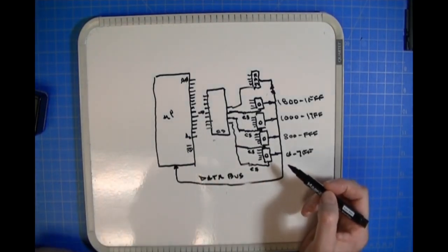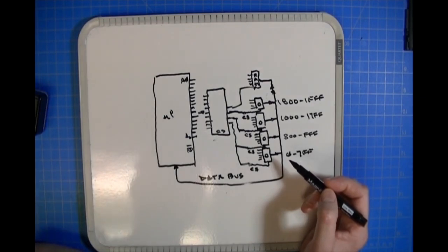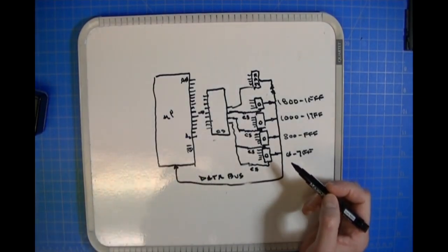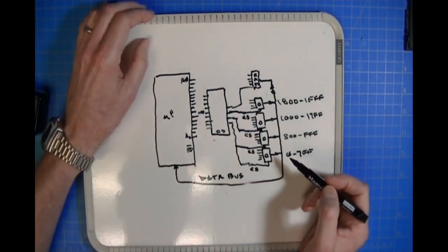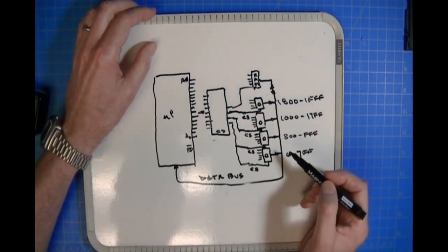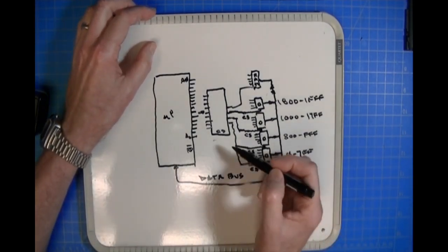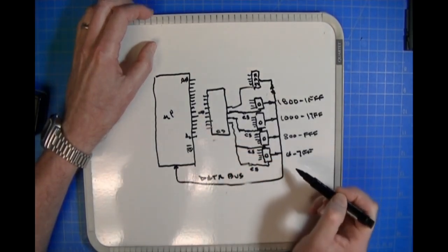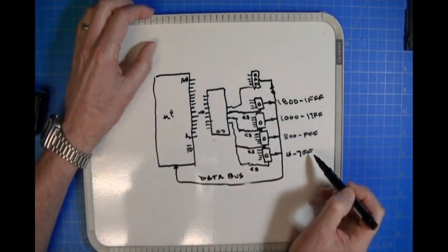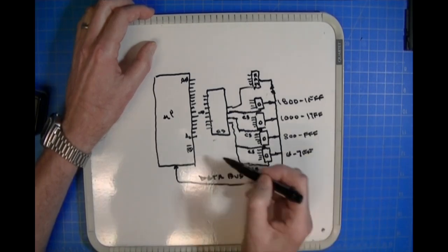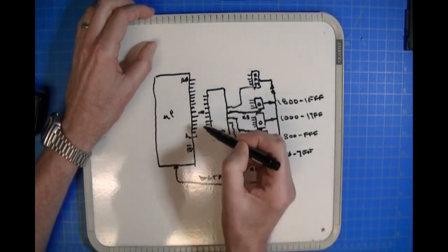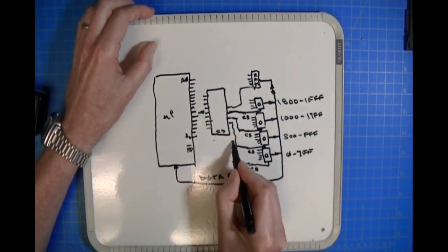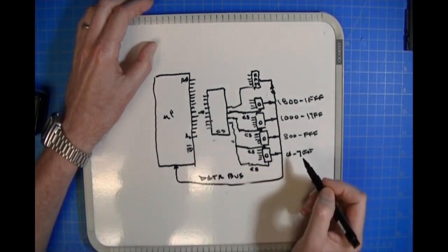Okay, so where before you were looking at multiple small-scale integrated circuits to do the decoding, now for the bipolar PROM you can say, okay, for the combination of bits between 0 and 7FF, whenever that combination of bits is on these output lines, this line is going to activate my EPROM 0, okay, first EPROM.